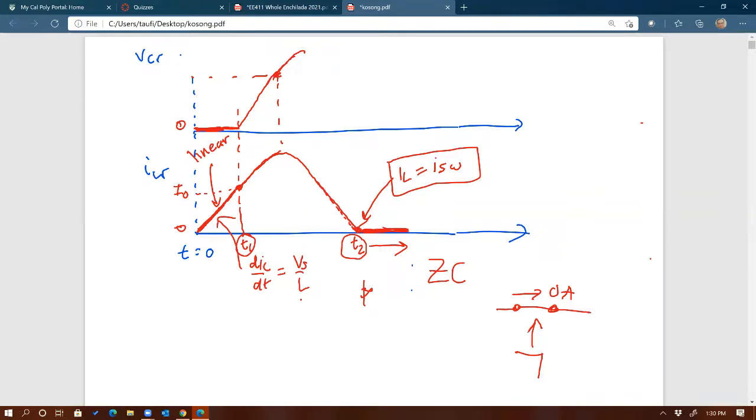Could it be modeled by a regular bidirectional switch in series with a diode? Yes, exactly. You could do a diode and then a bidirectional switch like a MOSFET. Yes, you could, definitely. That way it prevents current from flowing backward.